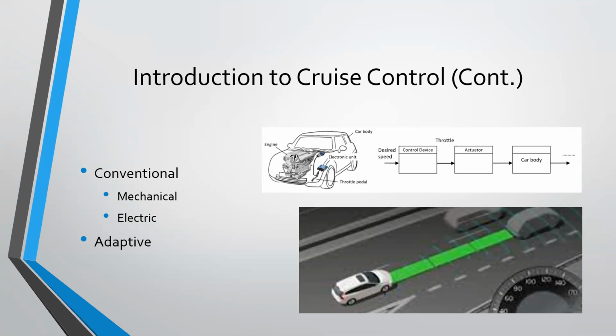In recent years, vehicle systems and controls have become highly sophisticated. Newer vehicles are now offering adaptive cruise control. Adaptive cruise control, or ACC, uses forward-facing cameras and sensors that can detect the distance between vehicles in front of the pilot vehicle. This system not only maintains vehicle speed, it also incorporates the braking system of the vehicle as well. If the forward-facing cameras or sensors detect that it is approaching a vehicle or obstacle too quickly, it will apply the brakes automatically to aid in the avoidance of a collision.